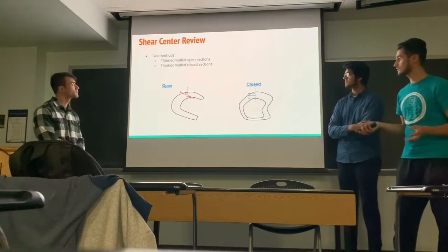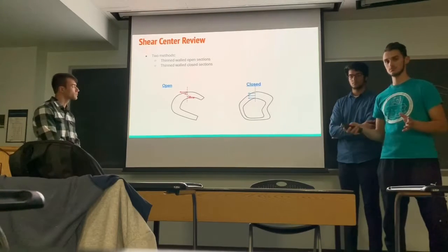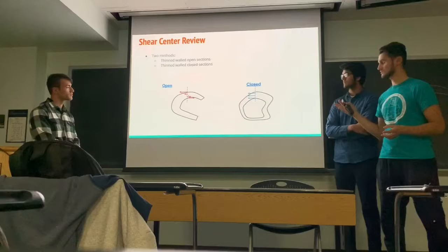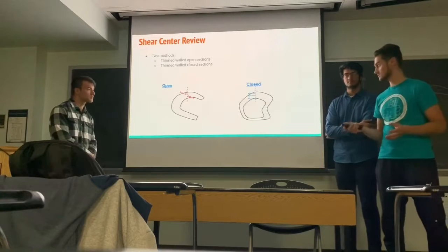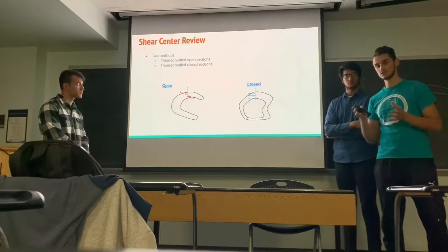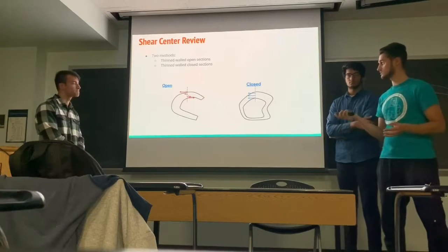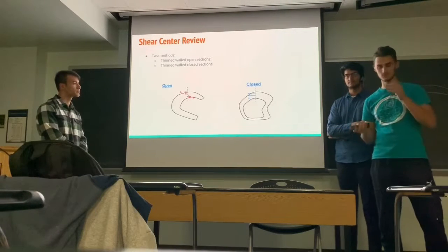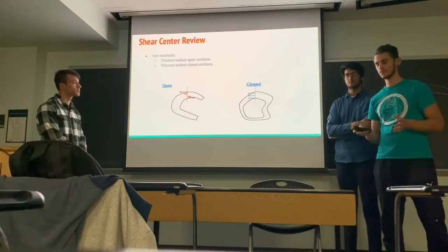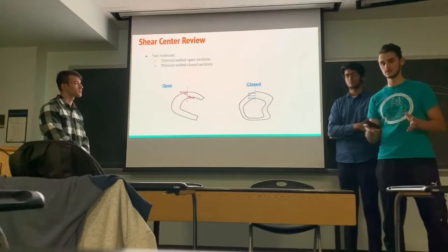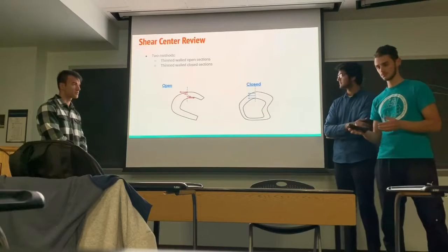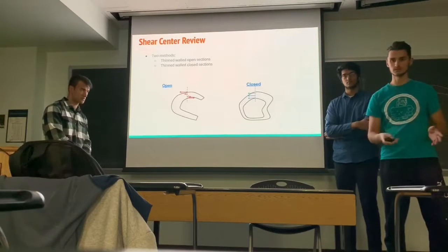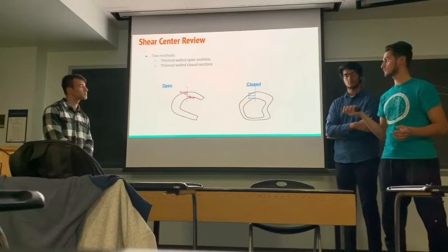So as a final note, this is basically 2 different methods on calculating both open and closed sections. Usually closed sections require a little bit more calculation, because now you have to take into account solving for the shear flow at the origin, which is typically 0 for open sections. So there's a little bit more work required with closed sections, but generally for closed sections you can apply shear loads at points off the shear center and still have the shear stresses caused by the torsional and shear loads be constant across the thickness. But that is generally not the same case for open section beams.